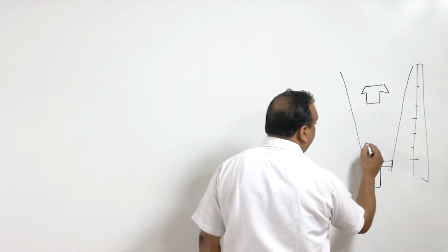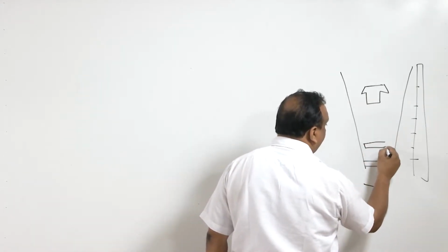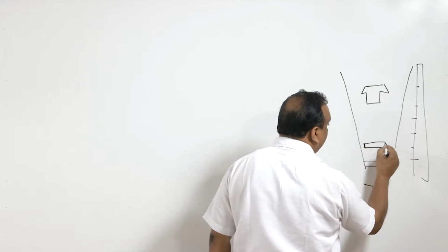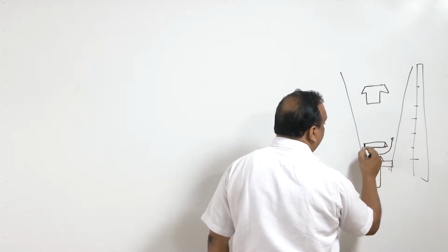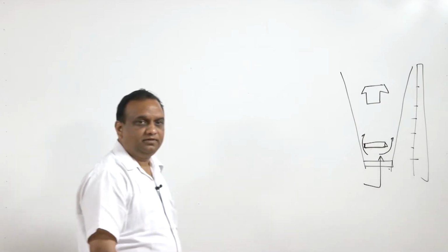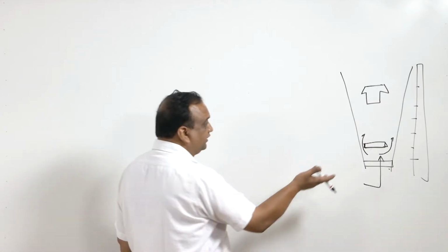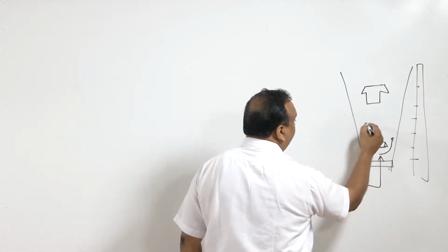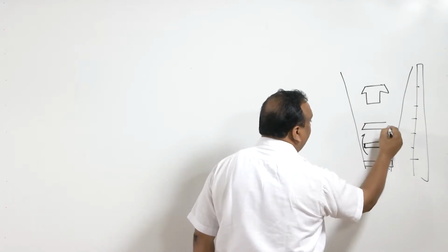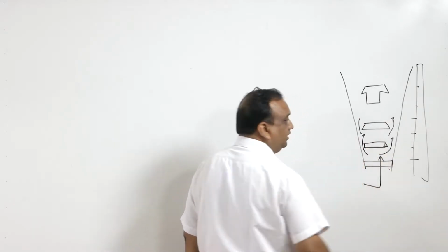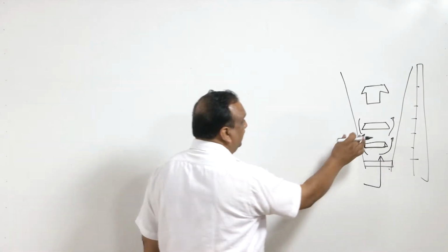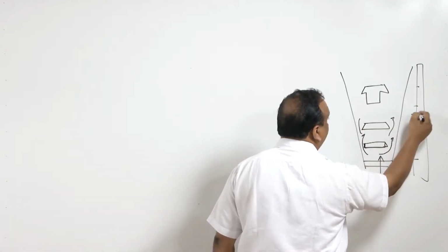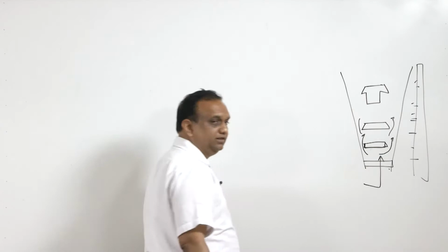When it goes up, from the sides of the bob, the water starts moving, right? It is further pushed. When it is further pushed, more space is available for the water flow, and the bob remains suspended in the fluid, and if there is a marked scale here, from the scale we can take the reading.